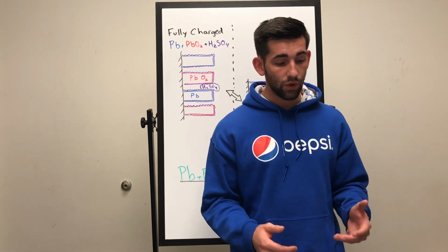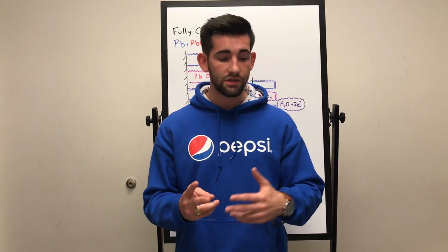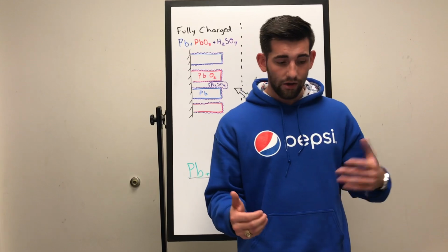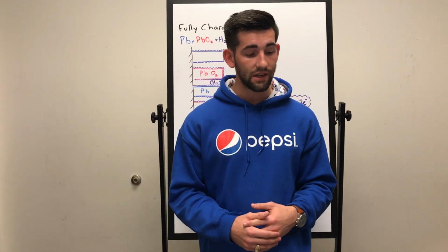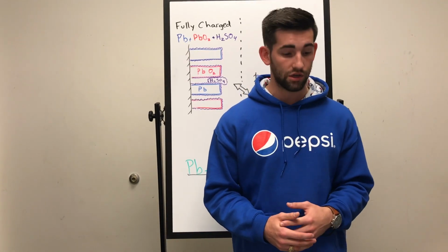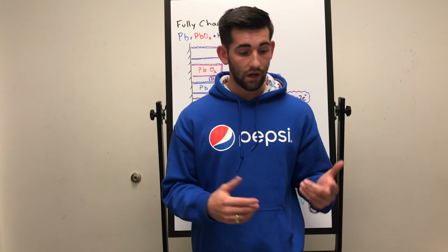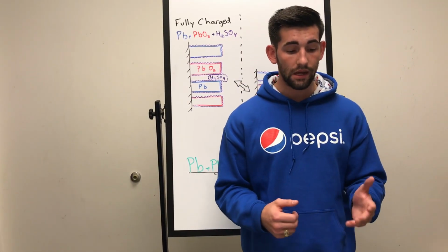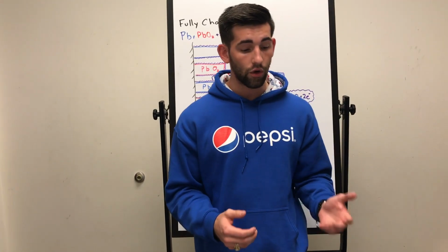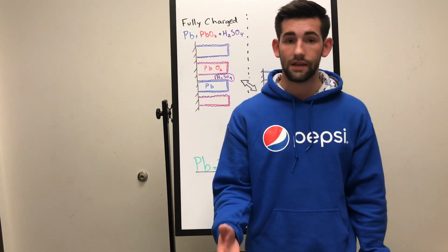It is a class of switched mode power supplies, SMPS, typically containing at least two semiconductors, a diode and transistor, although modern buck converters frequently replace a diode with a second transistor used for synchronous rectification, and at least one energy storage element, a capacitor, an inductor, or a combination. To reduce voltage ripple, filters made of capacitors, sometimes in combination with inductors, are normally added to such converters' output on the load side filter and on the input supply side filter.